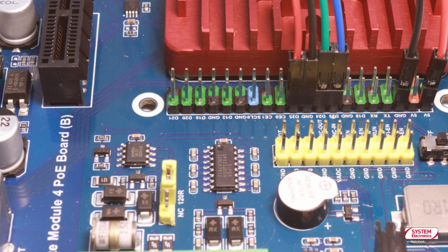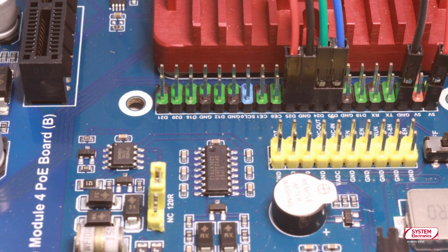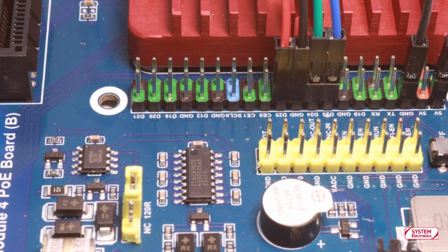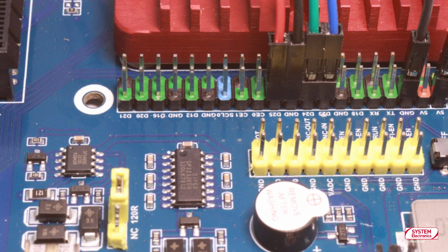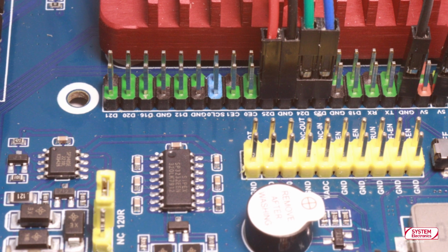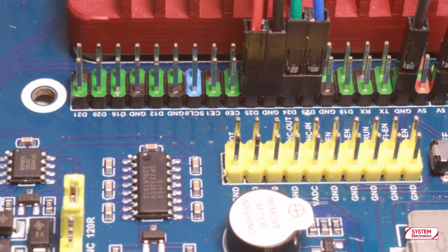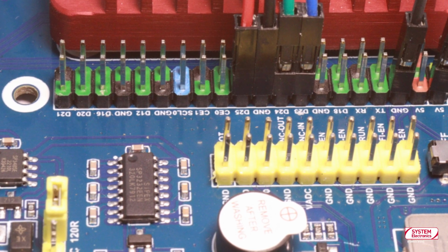Here is how to set up the hardware. First of all, connect the Astrial's ground to any CM4's ground pin and Astrial's VCC to any CM4's 5V pin. For this tutorial, we have used pins 2 and 6 as 5V and GND respectively.